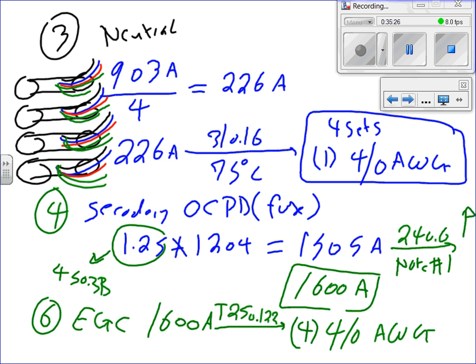Can you find a conduit that fits all these? 350s, 2 4s? Yes, no problem, assuming you're pulling a full insulated neutral and insulated ground. Any questions, my friends?